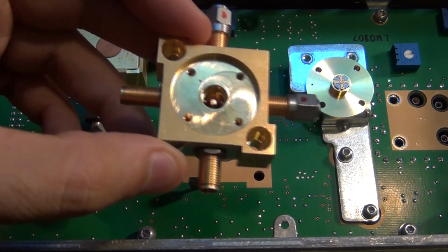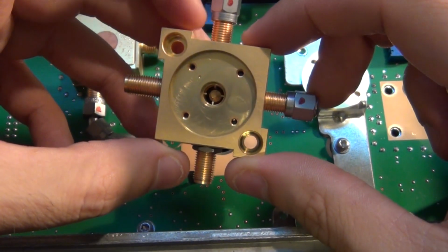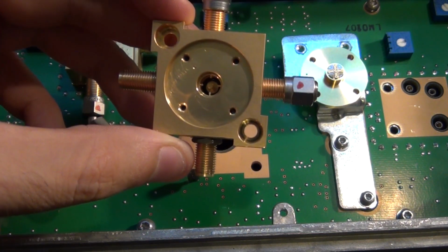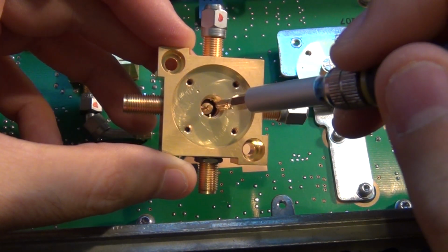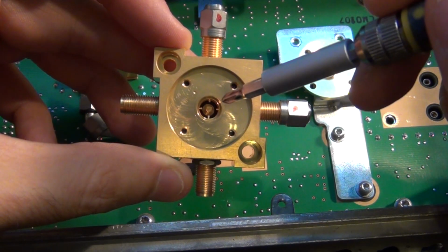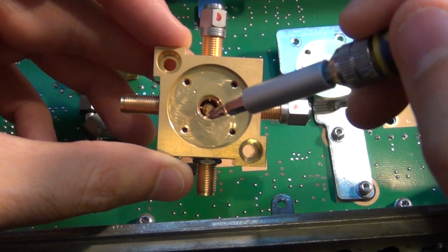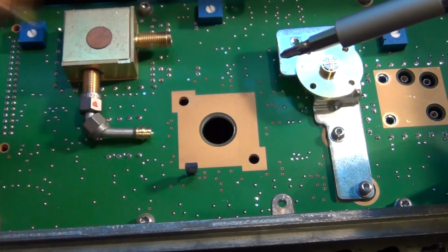Every time I take one of these things apart, I'm always amazed by what they have chosen to do. This is really, really interesting again. So the very large amplitude driving signal comes in on that center pin over there. And that center pin goes into something which I'm going to show you in a second, and then it's split into 1, 2, 3, 4 pulse-shaped impulse trains coming out of the step recovery diode.